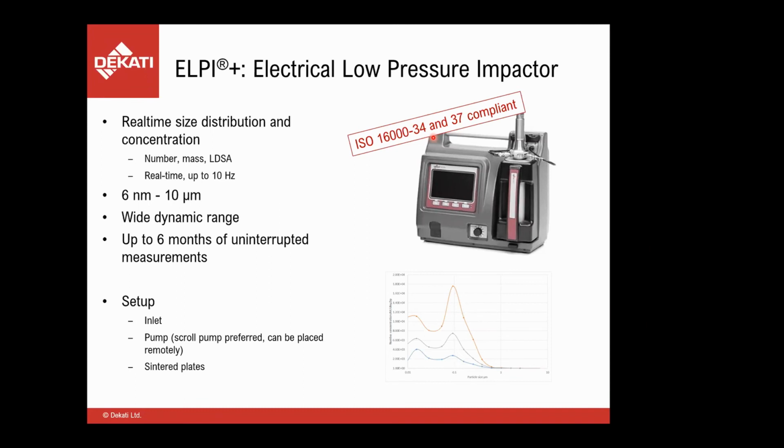We typically would use an inlet, a PM10 inlet or a TSP inlet, a pump. Of course, scroll pump is preferred, and the pump can, in these measurements, be placed remotely and use a long vacuum line. So it's away from the instrument itself. And of course, the sintered plates as the collection media.